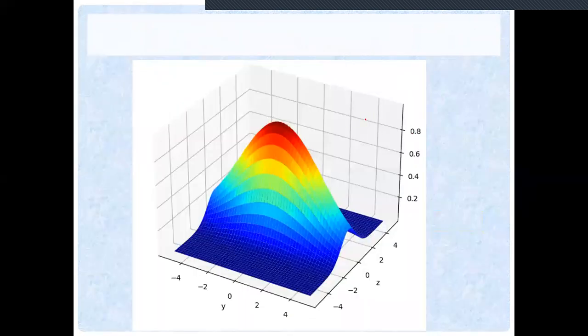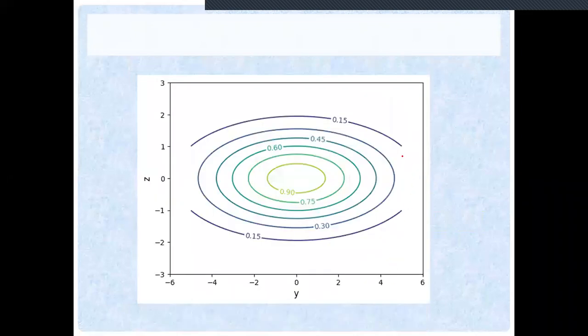This is the concentration shape, just to see that there are two normal distributions. One can be traced like this, in the y direction of the concentration, and one can also be traced in the vertical direction. That is like a cross section like this. This is not the symmetric one, since the dispersion in y direction and z direction are not equal. The contour plot would be represented in the form of concentric ellipses.